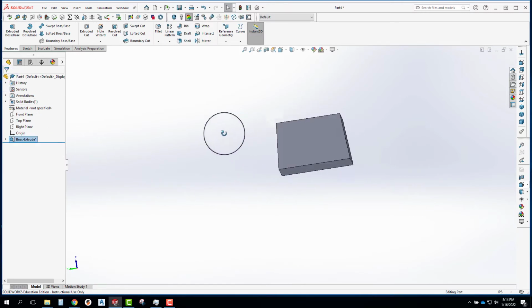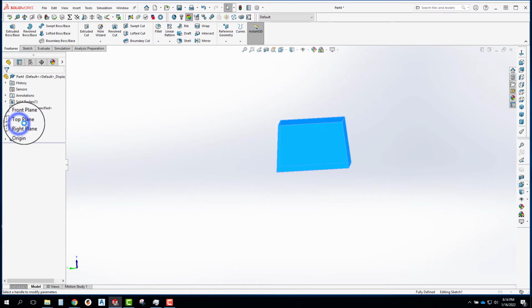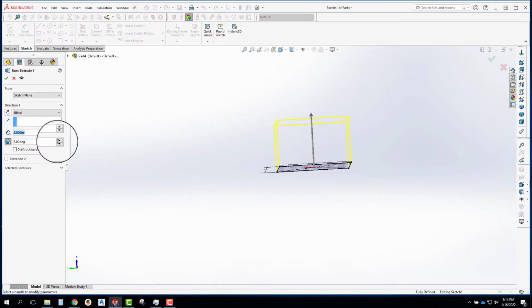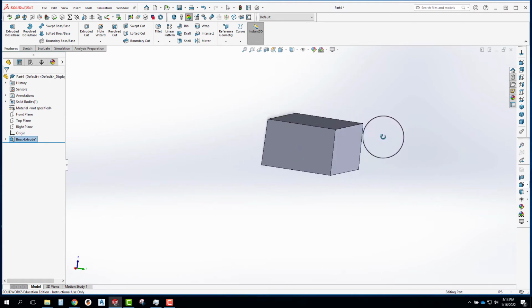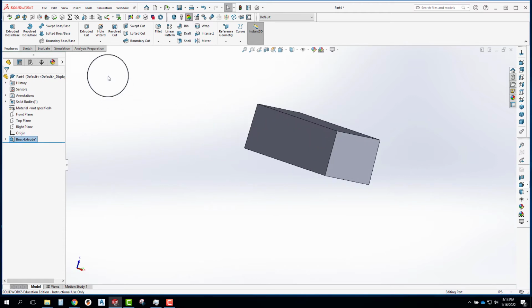You'll see that there's now a taper to the walls, and that makes it release easier from a mold. So 5 degrees taper is a lot. Typically you just have a degree or so of taper. So by putting in, let's just say 1 degree taper, I don't have to do the math to say how much it should come in over the length of the box, which you could do. We're going to get to the loft feature later. That's where you can connect 2 different sketches as an extrusion.